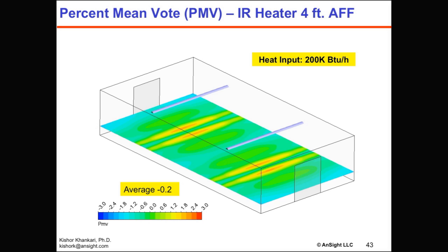This is a statistical thing. Well, the index of PMV, what we call it, goes from -3 to 3. -3 is a blue color. People will complain it's very, very cold. When it's 3, people will complain it's very, very hot. So ideally, we want to be at that 0 number, what we call thermal neutral environment. People are happy in that environment. So we want the green color.